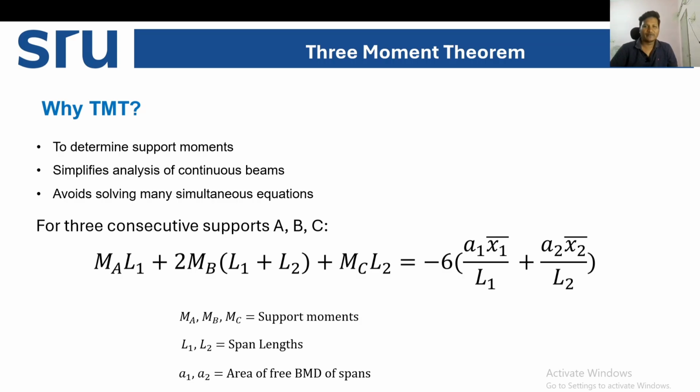Let us refresh the knowledge about the three-moment theorem. Why are we using the three-moment theorem? We are using it to determine the support moments. Then we can simplify the analysis of the continuous beam, and we can avoid solving many simultaneous equations. So this is the basic equation we have used in solving continuous beams by the three-moment equation.